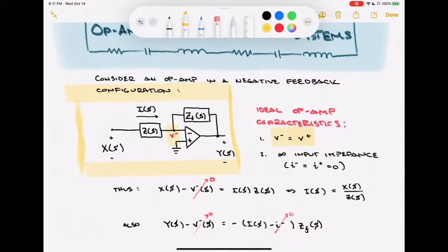The second one is that these op-amps are infinite input impedance devices, which really means that the current that is trying to potentially go into either of those input terminals, which I'm showing with some little blue arrows here, sees infinite input impedance, and that means that the currents are going to be zero. So we're going to have no current draw through the input sides of this device.